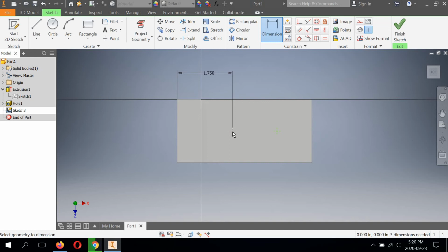And then from this one to the second one, it's a relative dimension. It's 1.5. If it was dimension from back here to here, it would be absolute, all coming from an origin of some kind, but this one is dimension from here. So it must not be that critical of a hole to be dimensioned that way. But we'll talk about something like that more in the future.